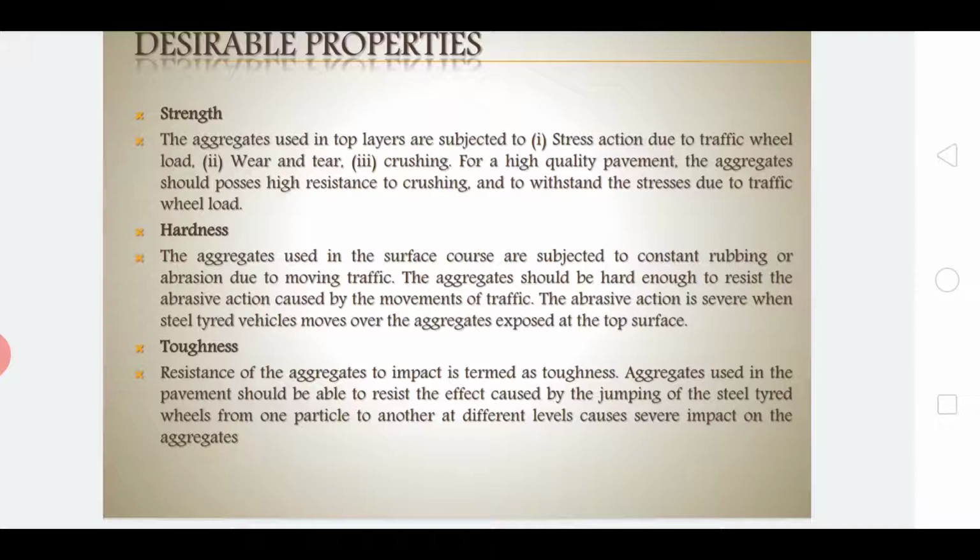As I mentioned earlier, it is constructed in various layers, and especially in the case of flexible pavement, when a heavily loaded vehicle is moving, load is transferred from grain to grain and affects the lower aggregates also, especially immediately after speed breakers or when there is a pothole.